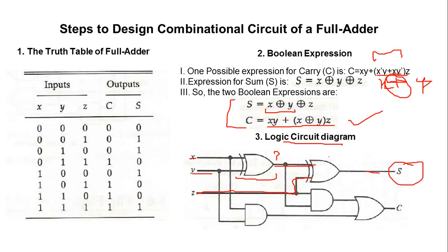But if we look here at this carry part, what do I need to have? I need one variable as xy, one logic gate. So this is nothing but an AND gate, right? So I need an XOR too and I need another AND too, right? And then in the last, I need an OR gate also to do the sum of all. So how is it going? For xy, as it is simplified here in the expression, I will be using an AND gate.